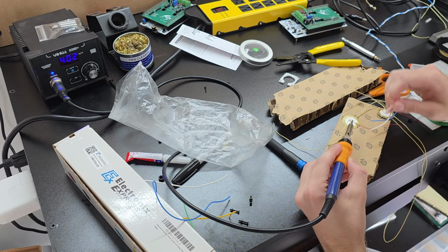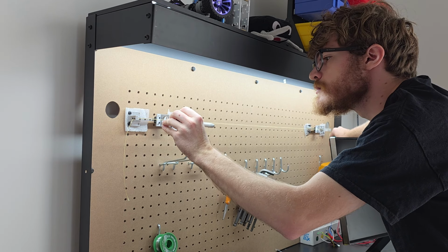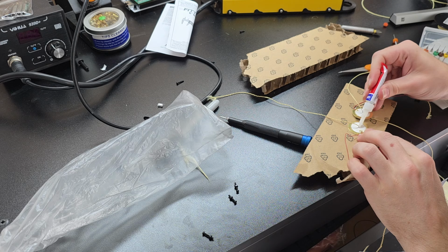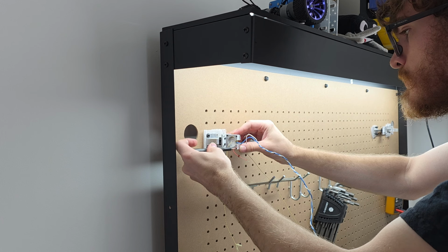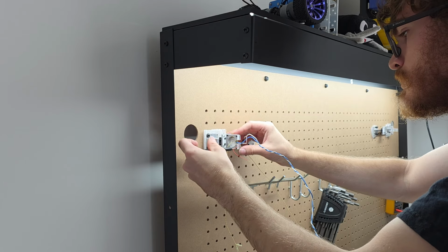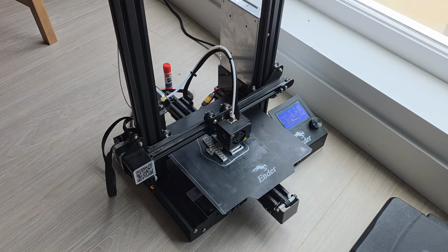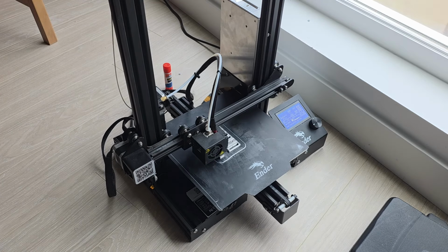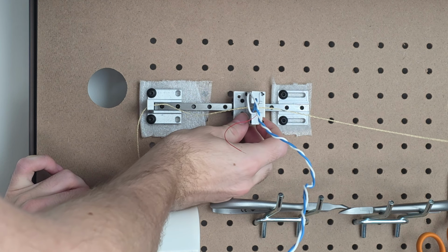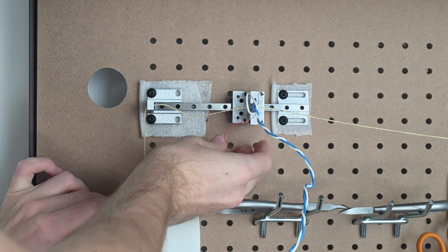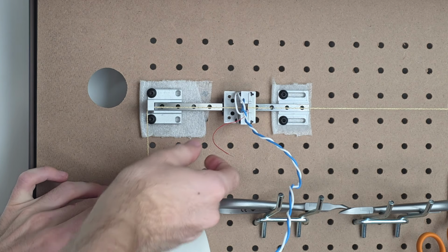We take these tiles, drill a hole through the center, thread the string through, and superglue the string into place. This gives us a solid connection between the string and the piezo, so the sound will transfer very efficiently. Then, I can mount the piezos in a 3D printed bracket that can slide on a linear rail. These rails are here so that when I hang a weight off the string to tension it, the piezo can slide back and forth until the tension on both sides is balanced.